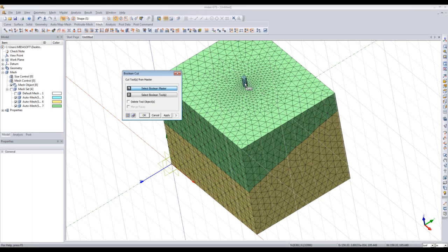So when you have a cylinder such as this, you said whenever you embed something, a third element is created, correct? Yes. Using this option, if you select delete tool object, it'll keep that element from being created. So in other words, it's a lot easier to make your cuts without having to worry about that. That's why I mentioned in my chat that instead of embedding, a boolean cut would be more effective, because it takes out that extra step. Okay.